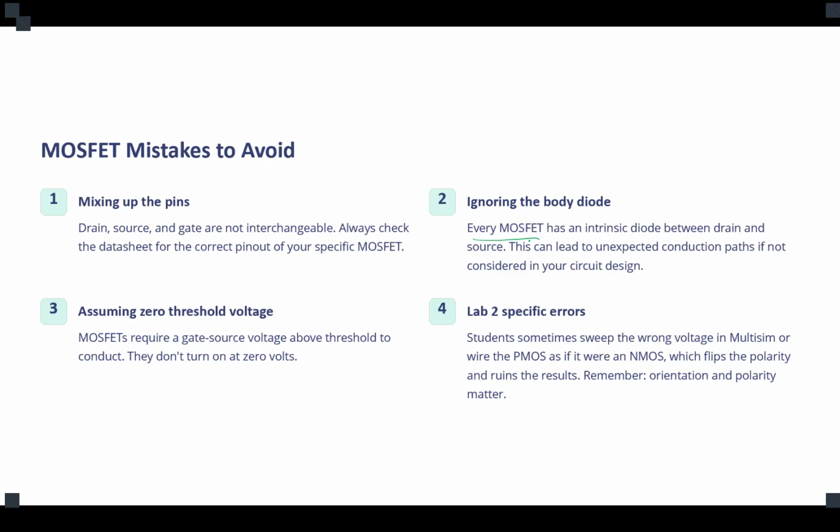The reason is because you normally use a MOSFET as a switch and you have a relatively high voltage between the gate and source and drain and source. So you don't actually use the diode state of the MOSFET in your circuit. So that reverse current is not in a state that you desire to have. You know what I'm saying? But remember, it is gonna be there and it is gonna affect the performance of your circuit. Is that clear? Are we good?